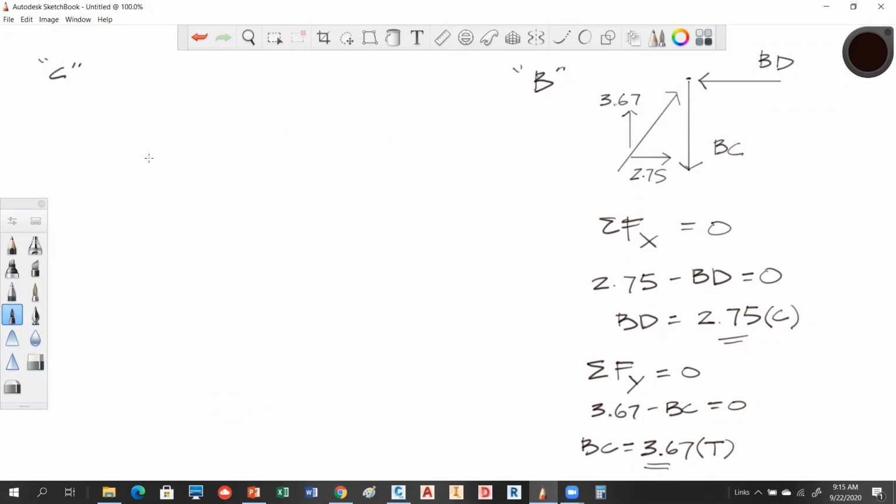Now, I always like to start with my joint, which I kind of didn't do in the other piece. I'm going to draw what I know coming into it, and then we'll label everything. So I know I have a vertical member coming into this, and I'm not going to worry about which direction it's acting yet. Actually, I know that one already, but we'll get to that. And then I've got two horizontal components coming into this.